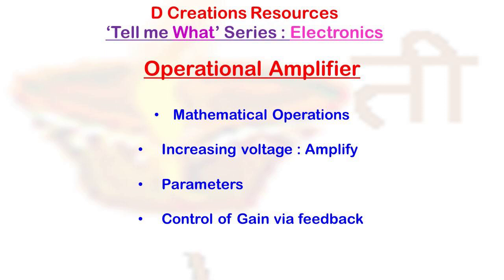Basically, differential amplifier. That means the circuit that amplifies the difference between two signals is an important part of an OpAmp. And so when I say differential amplifier, you can say that if V out is the output, then V output is equal to gain, that is A, into V plus minus V minus, where basically V plus and V minus denote the two input terminals.